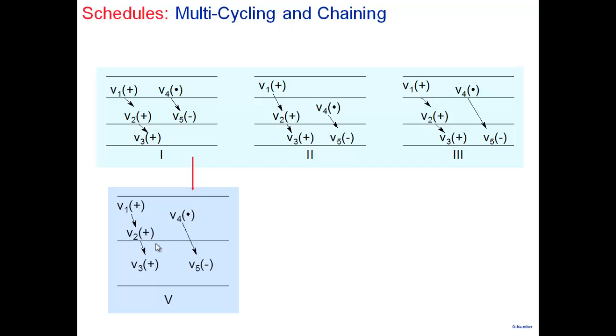So what I can do is have blocks which are adder-subtractor blocks, with a select input. If I give some select input, it adds. If I give some other select input, it subtracts. So here I require 2 adder-subtractor blocks and 1 multiplier. Here also I require 2 adder-subtractor blocks and 1 multiplier. So if we compare these 2, they are similar in terms of resources. But note, I require 2 clock cycles here.